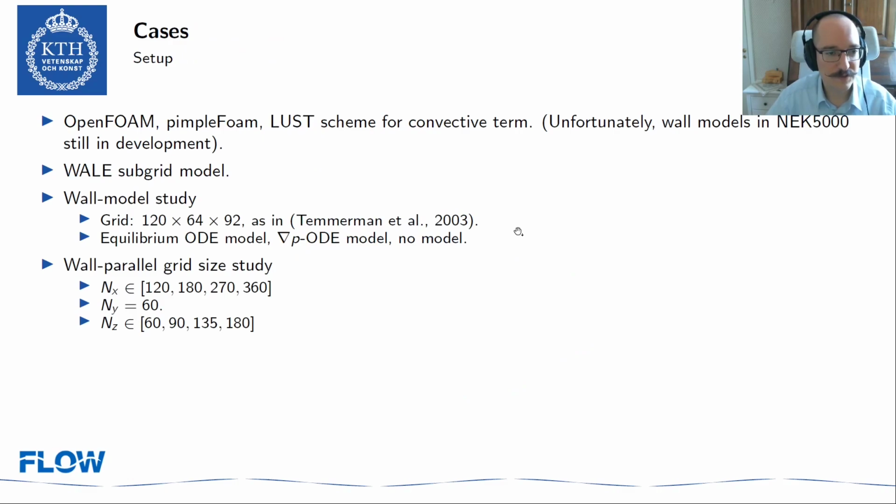This whole study is going to be conducted in OpenFOAM using the built-in pimpleFoam solver. Among the numerical settings, I would like to highlight the LUST scheme, which is used for the convective term. This is a blend between a second-order upwind scheme and linear interpolation.